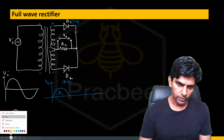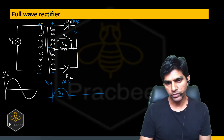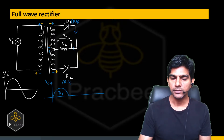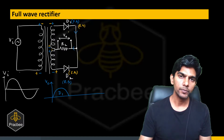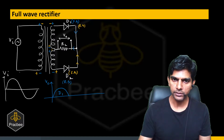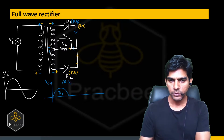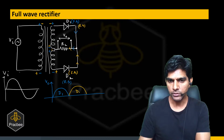Now, if we talk about the second half cycle, the top end of the primary will be at low potential, bottom will be at high potential. Similarly, the polarity will also reverse on the secondary side. So the top will be at low potential, then plus, and then minus, and then plus. Can you say now the diode D1 is reverse biased and the diode D2 is forward biased? Now when diode D2 is forward biased, it becomes conducting and D1 will become non-conducting. So now the current will flow like this. Can you see, even in the second half cycle, the direction of the current is same through the resistor. So we'll get this output. Can you see? And this output is because of D2.